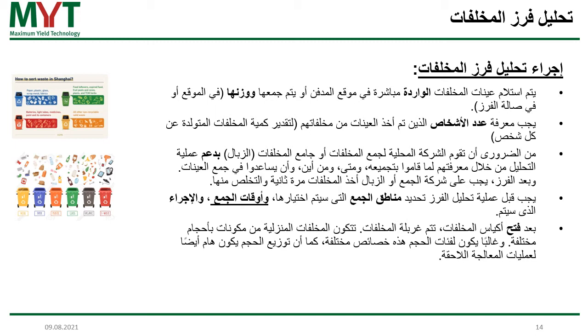And just to let you know how you start, of course, first you have to open the bags, and after you open the bags, the waste has to be sieved. Domestic waste consists of components of different sizes. This is the reason why we are sieving the waste. And these size classes often have different properties. So the size distribution is also of interest for the later treatment process. As I told you earlier, you need to determine the diameter of the holes in the sieve drum at the beginning of the separation process. And this is why you find out in the sorting analysis about the size of the different wastes.